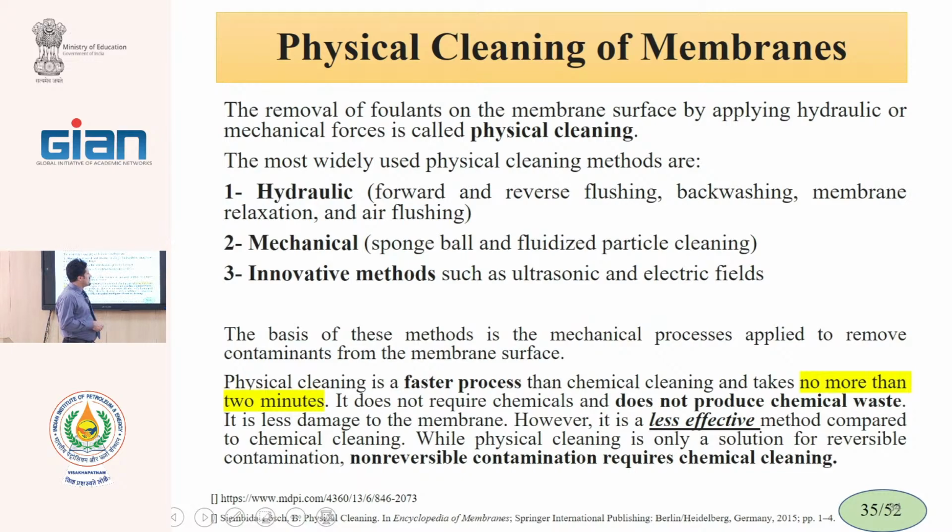Usually, physical cleaning is a few minutes in industry. For washing with acid or base, we usually use 1 hour. For mechanical and physical cleaning, we use 5 minutes because we want the water to wash the membrane surface.